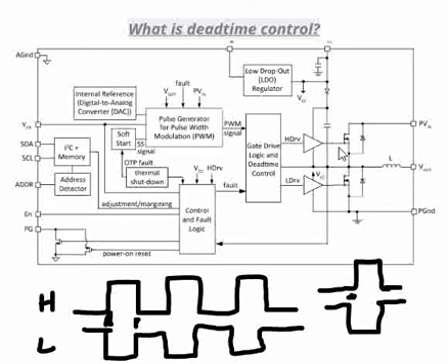So when you are using these kinds of configurations in motors, where you generate the PWM control to the DC motors, the control circuit, PWM control circuit, which the microcontrollers, for example, are going to generate, you have to ensure this dead time is implemented.